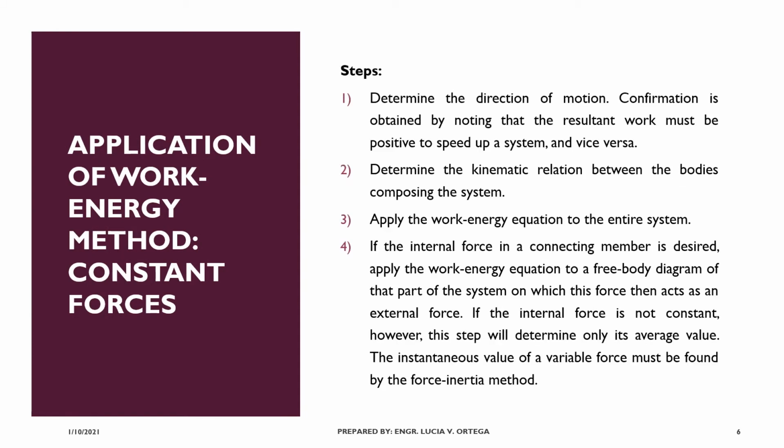So here is the procedure on how to apply the work energy method for constant forces. First, determine the direction of motion. Confirmation is obtained by noting that the resultant work must be positive to speed up the system, and vice versa, meaning all forces opposing the motion are negative. Then determine the kinematic relation between the bodies composing the system, and then apply the work energy equation to the entire system.